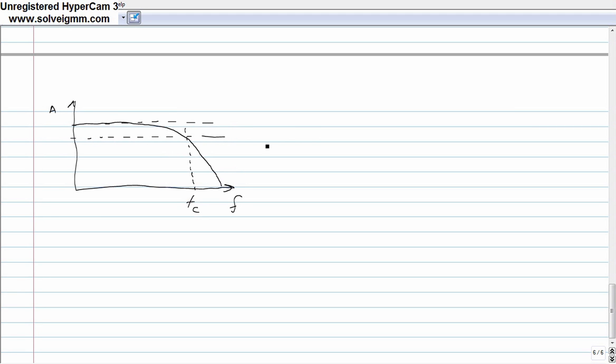One of the first things you should notice is f sub C occurs after the amplitude has started to dip. This area here is called the roll-off. And f sub C occurs a little while after it started to roll off. It occurs at a very specific point, which we'll talk about in just a little while. Now, this slope here, which I haven't depicted very well, is a constant slope. And in the case of this filter, it's negative 20 dB per decade. Remember, dB is decibels.